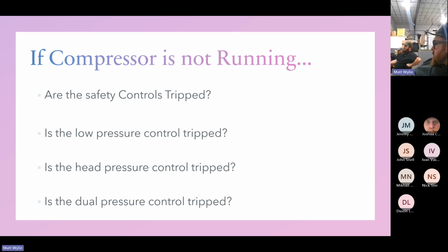If it's 208 and it's open, what's your voltage across it? It'll be 208, right? Yeah, because it's split phase, you're getting both legs. And what do you have to ground on each side if it's 208? 120. It's only going to control one leg. You still have 120 to ground on both sides on a 208 switch if it's open, because it's always back feeding through the second leg.